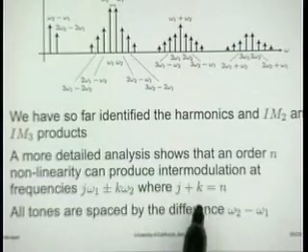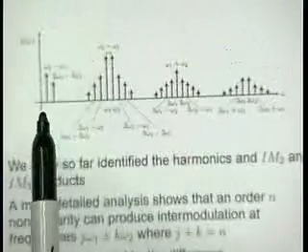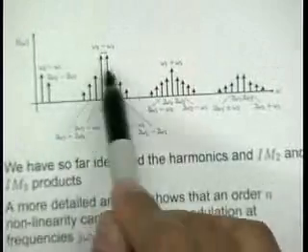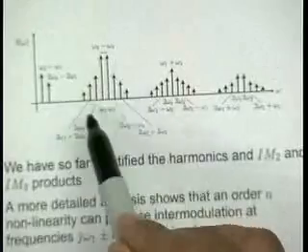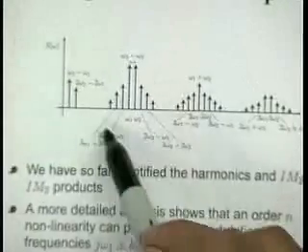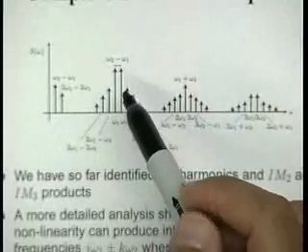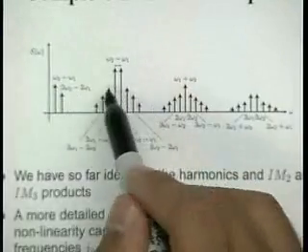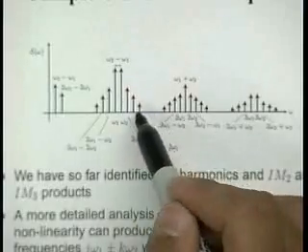So in general, all odd order powers generate distortion products which basically go right next door to your fundamental signal. So if you're worried about in-band distortion, you really worry about odd order distortion. In particular, the strongest term is your IM3 term. And then next you have your IM5, and then you have your IM7, and so on and so forth. Okay?